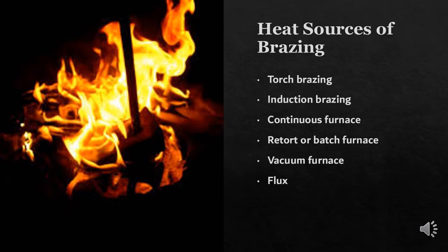Torch brazing means a heating source supplied by a fuel gas flame. Induction brazing means electric coils designed for specific joint geometries are used to heat the part and the brazing filler material until the liquid metal flows via capillary attraction into the joint itself. Continuous furnace means conveyor belts transport the pre-alloyed components through preheating, heating, and post-heating zones, where the brazing alloy reaches temperature, then resolidifies during cooling.